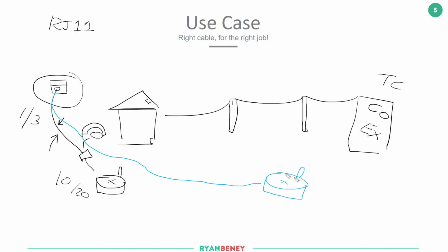The problem with this is that this particular RJ11 cable, as we know, has just 2 bits of copper in it. And this copper's not twisted or doing anything special to help with cable resistance or external interference. So essentially this poor cable, being designed for telephone and not really for extending your router, starts to degrade the overall service.